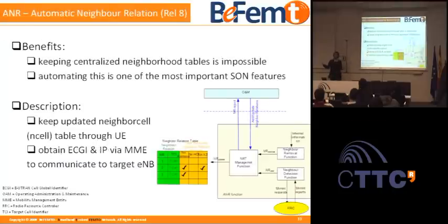So you start using the mobile phone to do this business for you, because that mobile phone, which is placed in a mutual coverage area, is able to see you and is able to see your neighbor. So therefore, there are all the protocols in place which allow you essentially to discover your neighborhood via the mobile phone. You then piggyback that to the operational management, and it will tell you whether this is a base station which you're not allowed to remove from your table. It's a base station which you're not allowed to do a handover to. It might also be a base station which has different features.